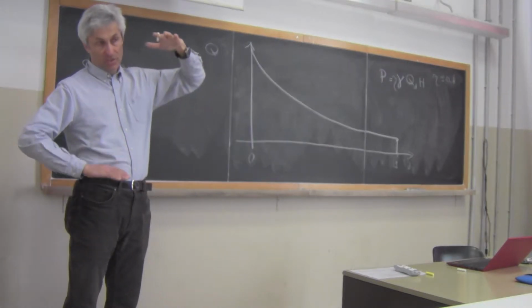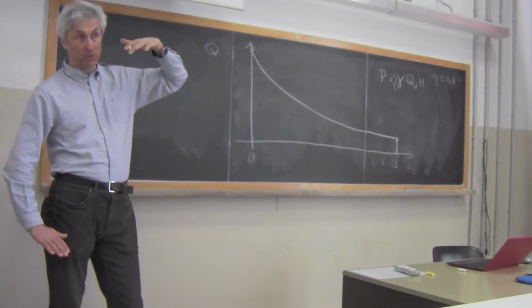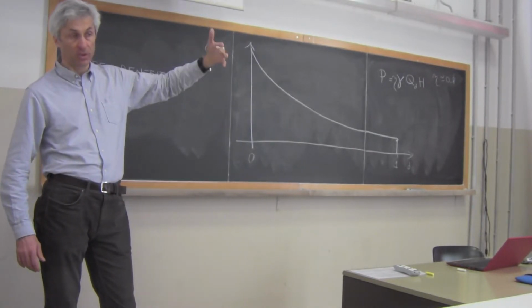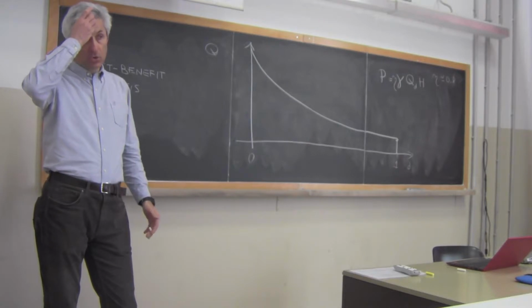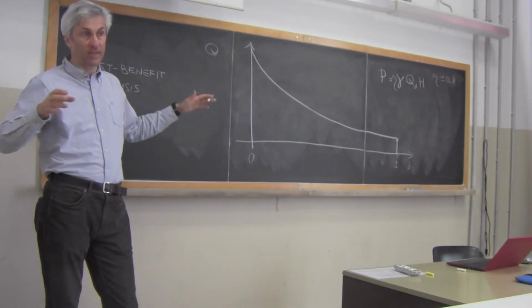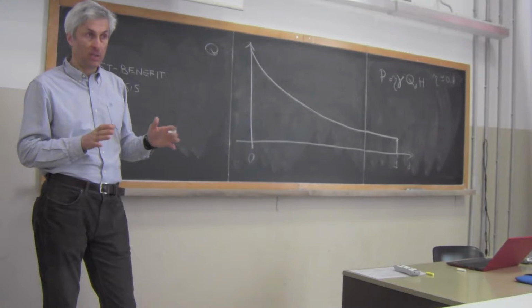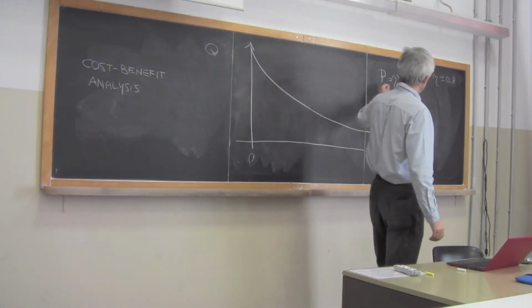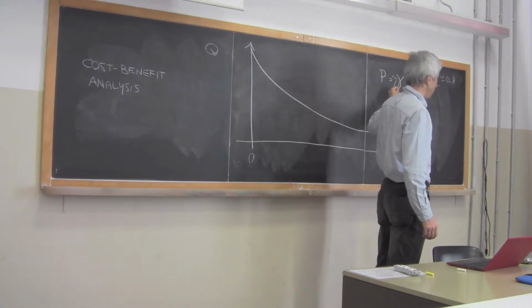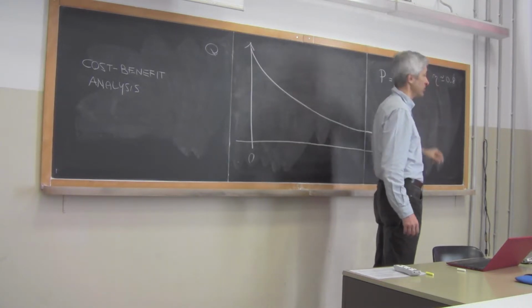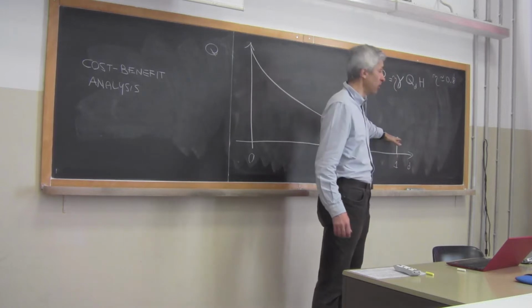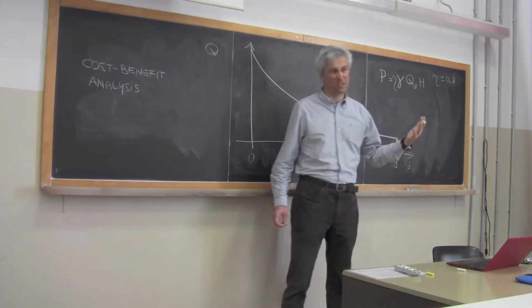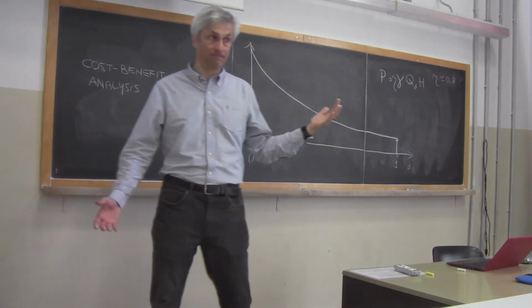If you have much hydraulic head over the turbine, you produce more energy. Usually in run-of-the-river plants, the head is limited. But you see that the power that you get is directly proportional to efficiency and design flow. So if you design for a low flow, the power that you get is reduced.